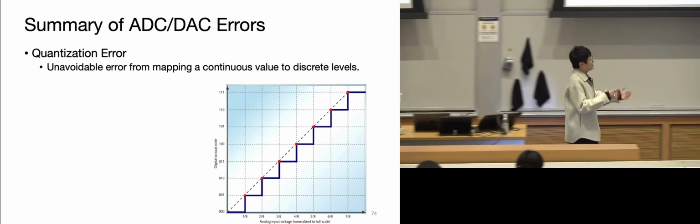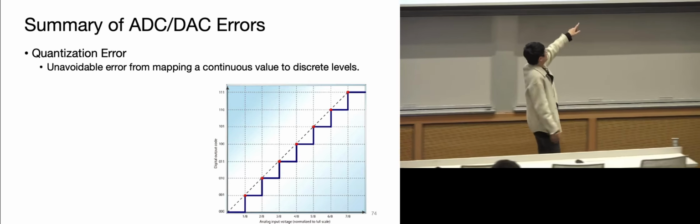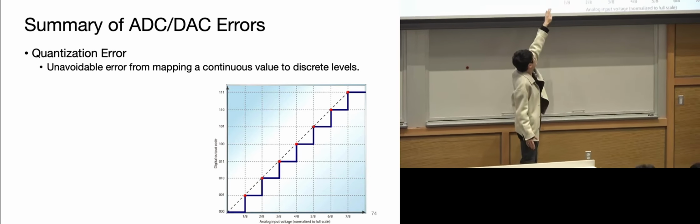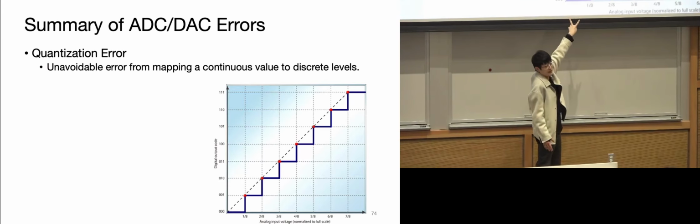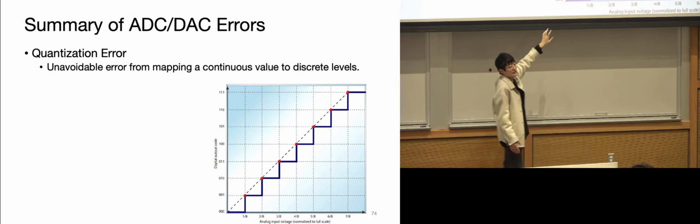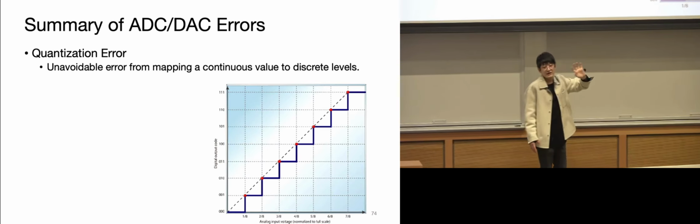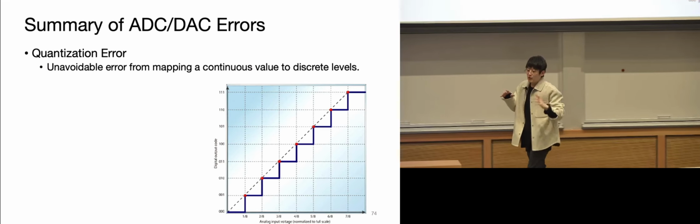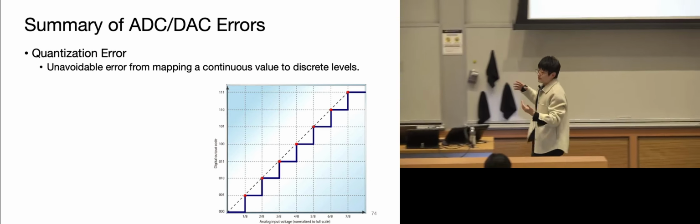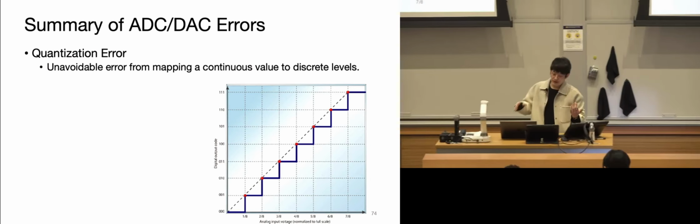Technically, this should be a continuous value in between, but since we only have so many bits, there is this error that can happen on each value. The worst case, if it's implemented well, will be 1/2 of the least significant bit.